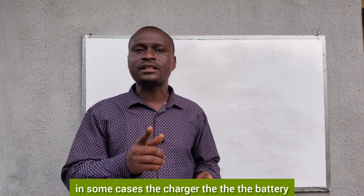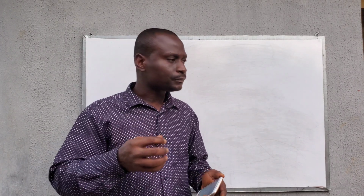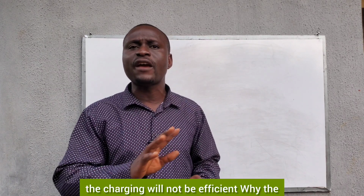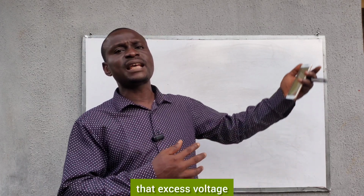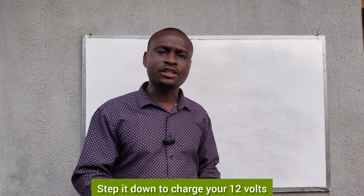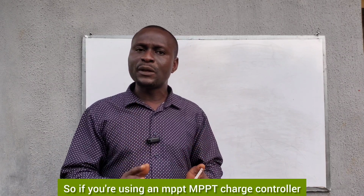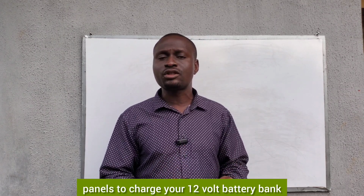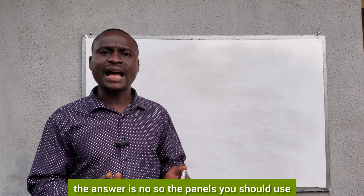In some cases, the battery will not be charged even when the intensity of sunshine is high. The charging will not be efficient. Why? The PWM charge controller cannot convert that excess voltage, step it down, to charge your 12 volt battery. So if you're using an MPPT charge controller, yes, you can use 2 pieces of 320 watt solar panels to charge your 12 volt battery bank. But if you are using a PWM charge controller, the answer is no.